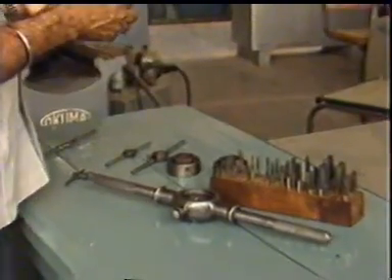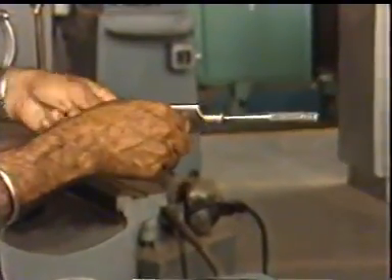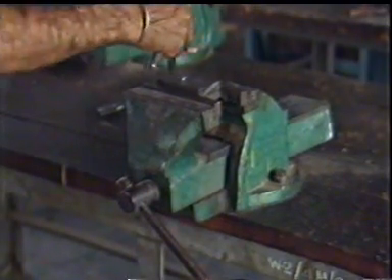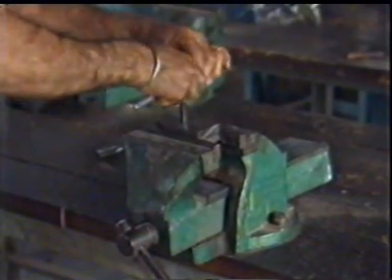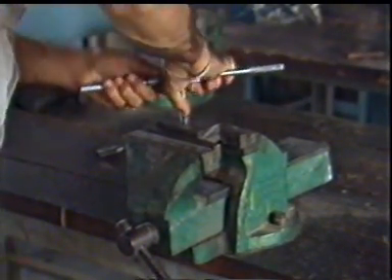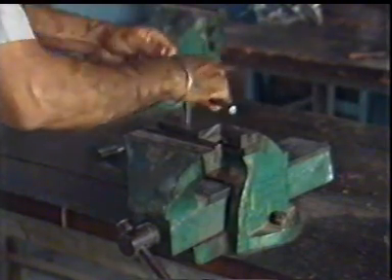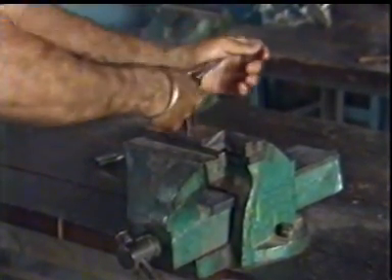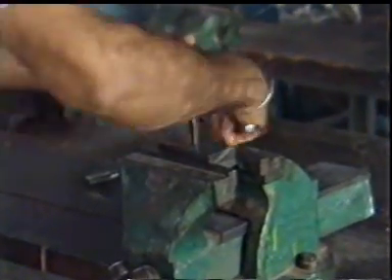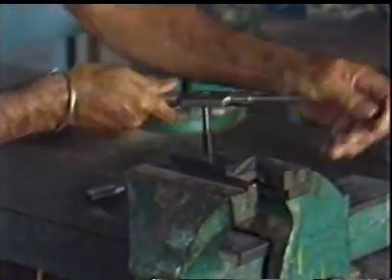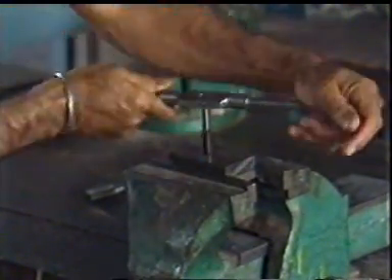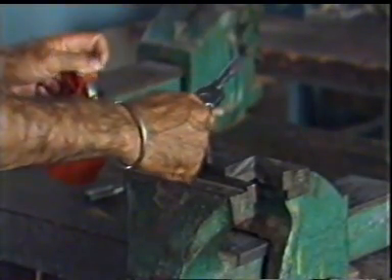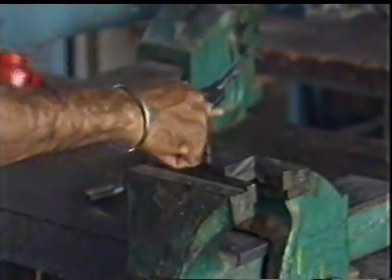First of all, a taper tap is taken and properly secured in a tap wrench. When starting the operation, care must be taken to keep the tap perpendicular to the work. The tap should be revolved only half a revolution at a time and then reversed in the direction of rotation. This will facilitate the breaking of metal chips and avoid clogging of tap.